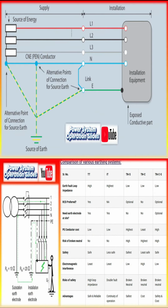TN system. In a TN Terra neutral system, one point of the transformer, often the star point, is directly earthed at the source and serves as the neutral. The exposed conductive parts at the consumer side are connected directly to this earth via the neutral conductor.